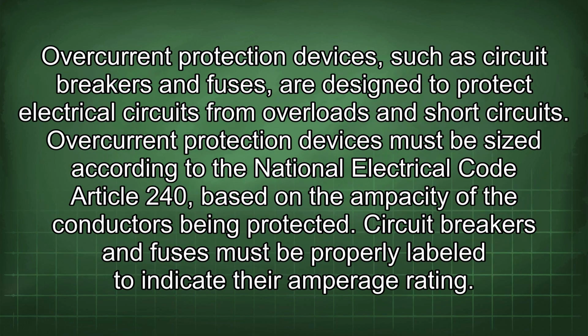Overcurrent protection devices, such as circuit breakers and fuses, are designed to protect electrical circuits from overloads and short circuits. Overcurrent protection devices must be sized according to the National Electrical Code Article 240, based on the ampacity of the conductors being protected. Circuit breakers and fuses must be properly labeled to indicate their amperage rating.